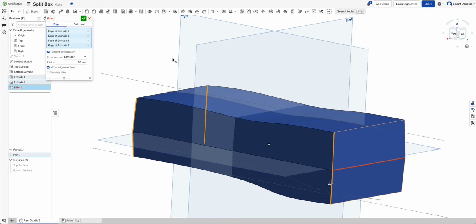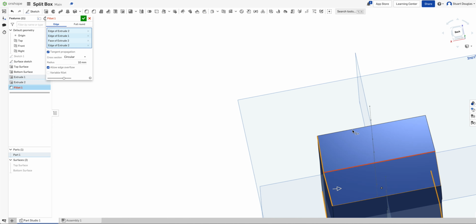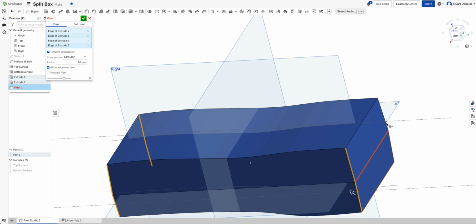Okay, and as you can see, suddenly it stopped working. Now if you encounter something like that, notice this line here has gone red, then what we need to do is remove it. So rather than cancelling all of this, let's just deselect. Okay, and let's deselect. There we go. Now we're back. That happened because I accidentally picked this line. So if that happens, don't suddenly click on the cross, just remove your selection from this box here.